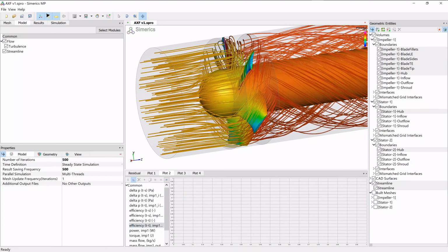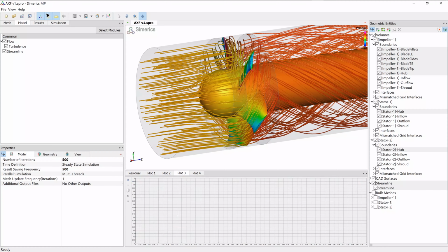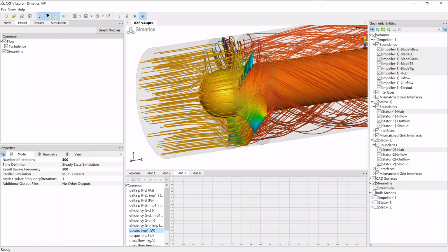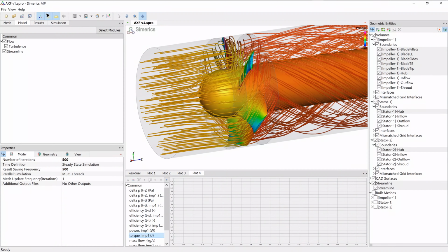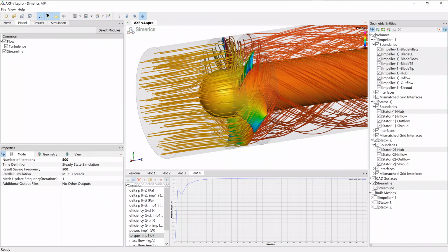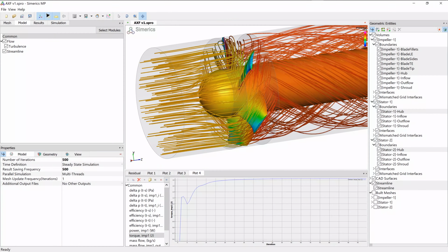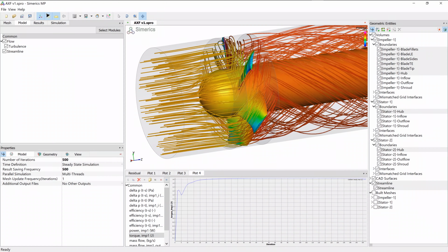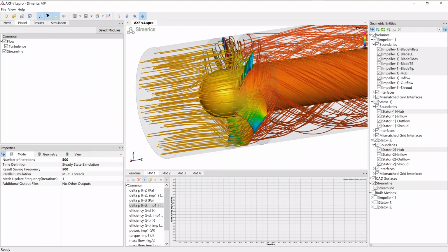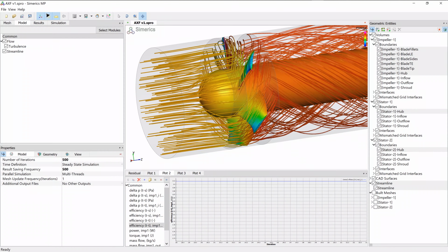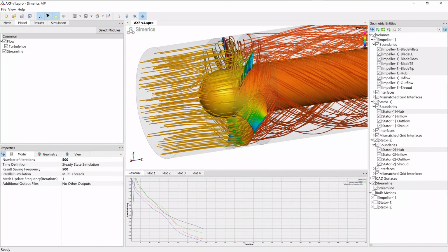We see here a converged solution for the steady-state simulation. We always recommend doing transient flow simulation to get a higher level of accuracy in your predictions. We always recommend 3D CFD simulations to evaluate turbomachinery components designed in CFturbo. In recent years, it has become more and more affordable to combine turbomachinery design software and CFD codes with optimization algorithms due to lower computational cost. In case design adjustments are necessary, after evaluating the simulation results, you can go back to CFturbo and modify the fan interactively.